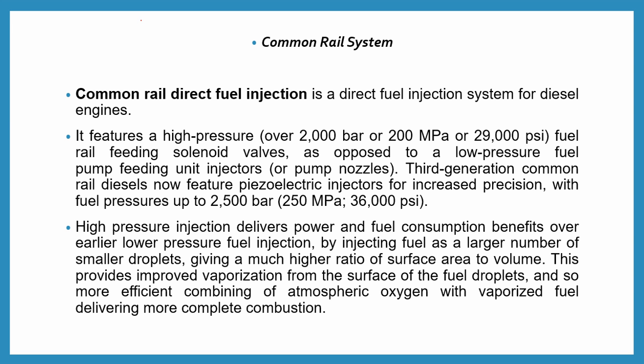Basically it features a very high pressure fuel rail, over 2000 bar, which feeds the solenoid valves, as opposed to a low pressure fuel pump feeding a unit injector.